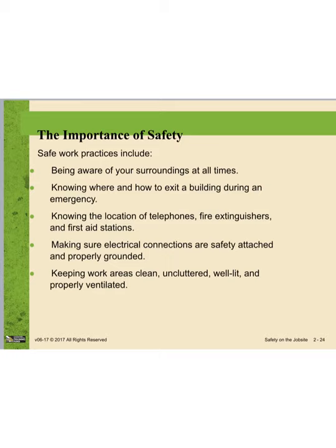That means you need to check the cords of power tools to make sure that they have the 3 prongs, that the cords are not frayed, and that there's no exposed wires. And make sure you keep your area clear. Clean up after yourself after you're done, and make sure that you're using proper ventilation.